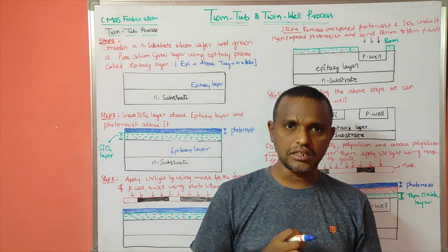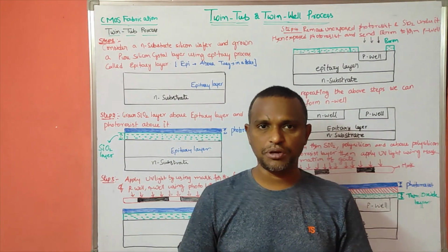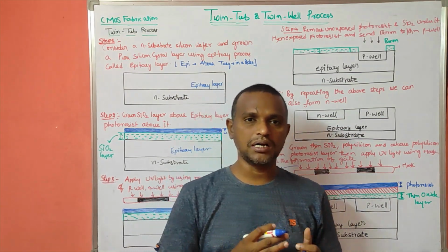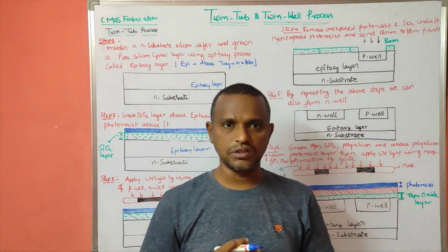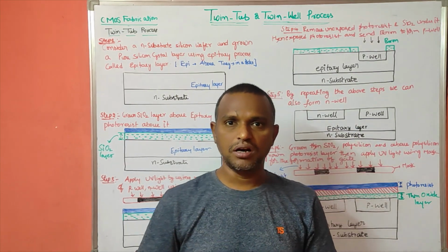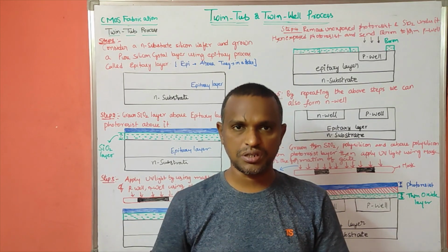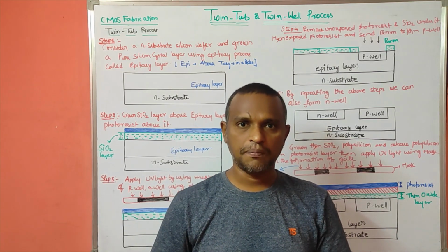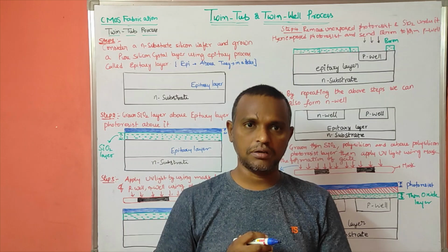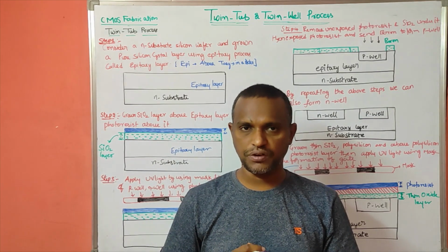That is another advantage. At the same time, whatever transistor parameters we have for the PMOS and NMOS, that is threshold voltage and body effect, and at the same time channel conductance and transconductance, all these parameters we can set separately for these transistors. So those are the advantages we have here.